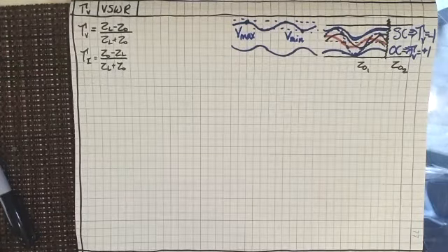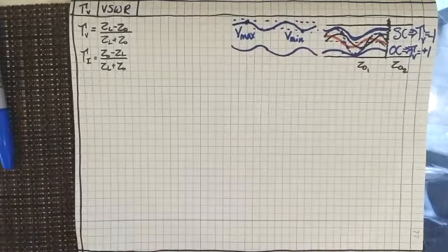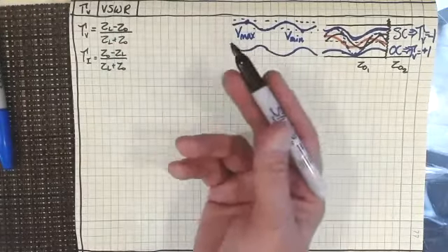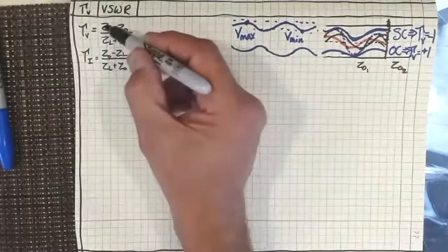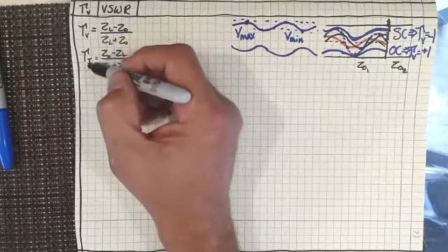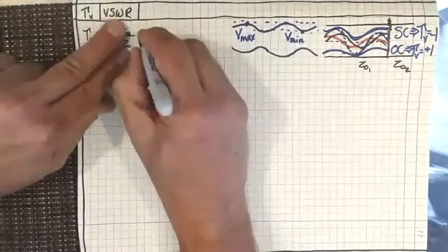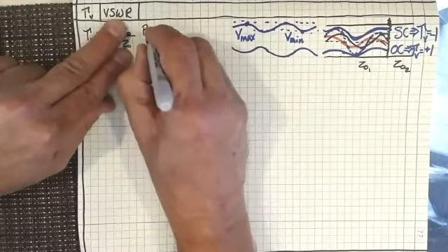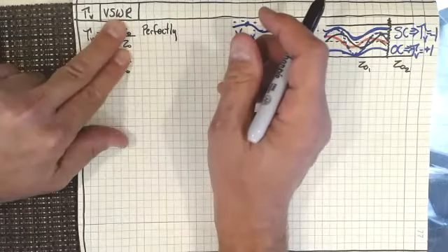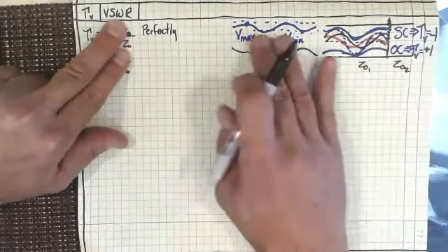So that's what I wanted to look at, these various different cases. We've got the reflection coefficient here. If I did have a perfectly matched case, this would be 0, right? So my reflection coefficient for both my voltage and current would be 0 if I have a perfectly matched case. And of course I would have no reflection at that point. So the wave would just travel through.